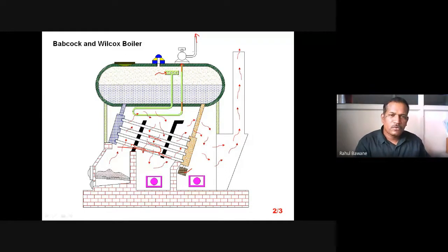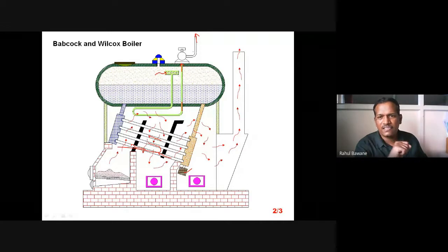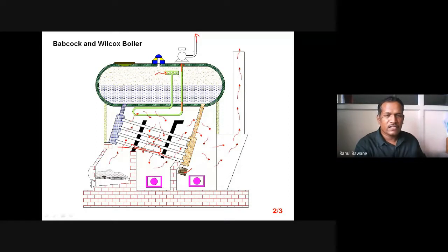Secondly, another mounting is called a fusible plug. In a pressure cooker, you observe that there is a fusible plug, a hexagonal shape, a button kind of structure on the lid of your pressure cooker, and that is the fusible plug. If you closely observe it, at the center there is a black material. So imagine your cooker doesn't have sufficient water. Whatever heat is supplied to your cooker is not utilized for generating steam or cooking the food. So where is that heat going? It is heating the overall body of the pressure cooker, and it might be possible that after some time it will blast.